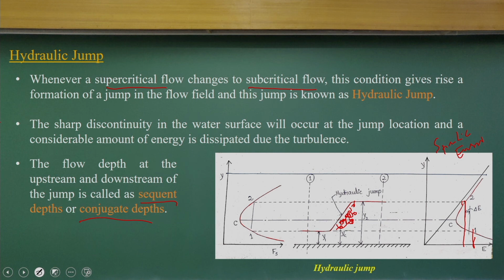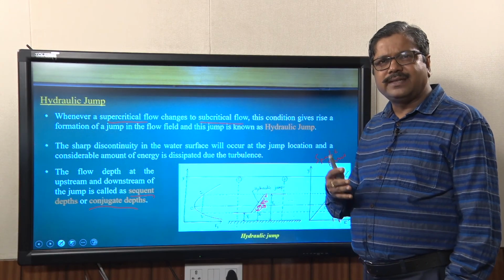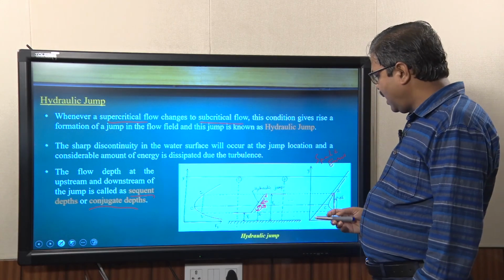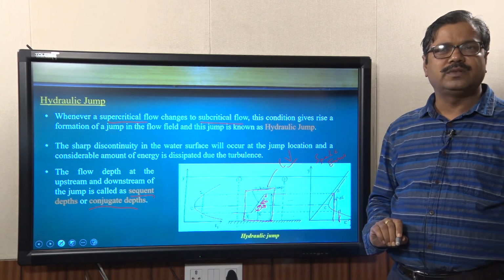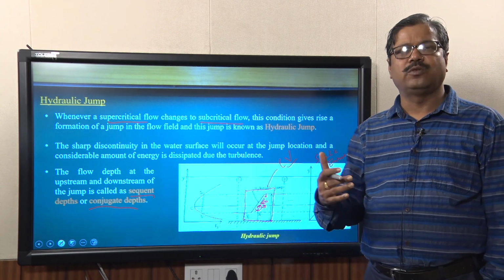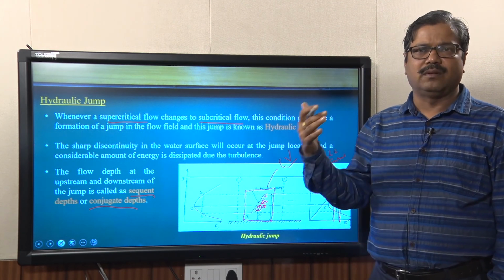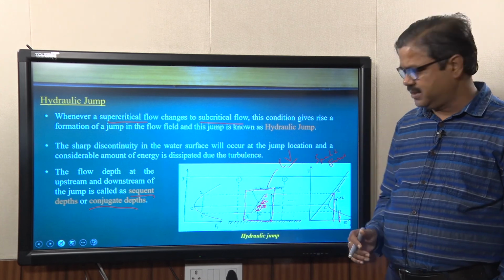Let me look at these hydraulic jumps as part of the specific force concept. When you consider the specific force concept, I can use a control volume like this. When I use this control volume, we look at what forces are acting on the control surface.